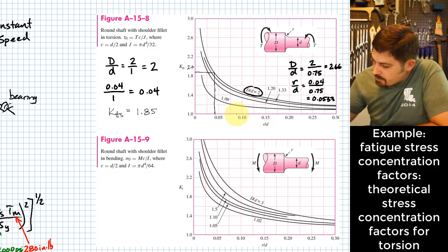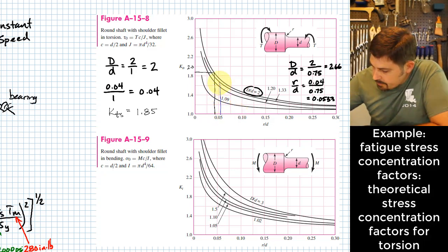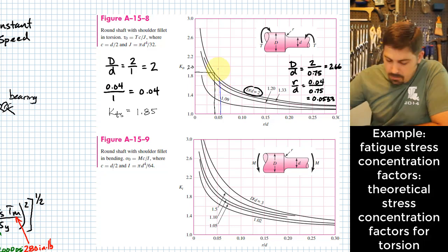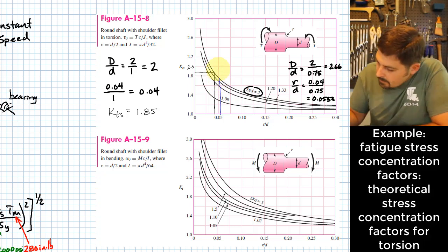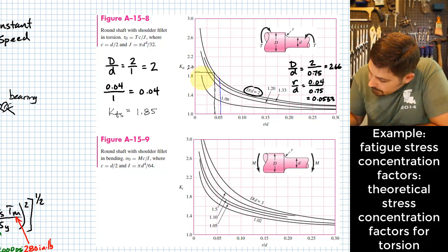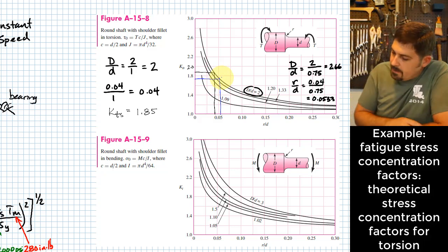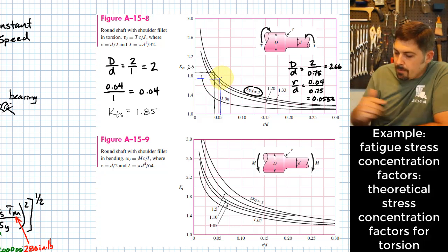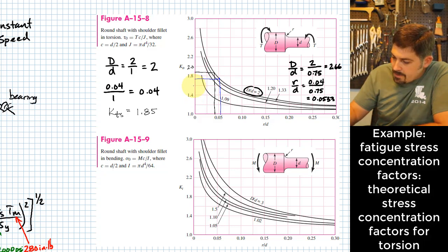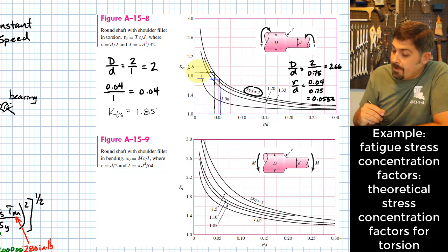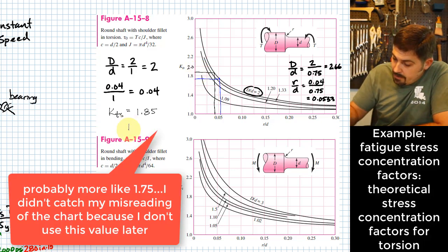We'll change the color here a little bit. It ends up that I'm just barely to the right of this location, still going up and reading to this point on the chart, and reading over here, something like this. With 1.4, 1.6, 1.8, in the middle there would be 1.5. I'd say that's about 1.55. So here the other K sub TS is equal to 1.55.